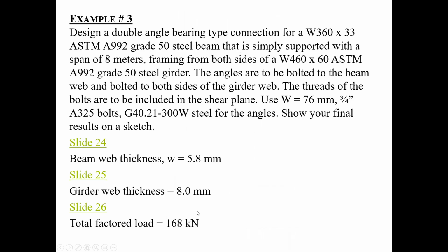So there you go. The total factored load is W, so 168, and of course half would go on one side, half, therefore my VF value is relatively small, 84 kilonewtons. So that's what I'm gonna be designing for.